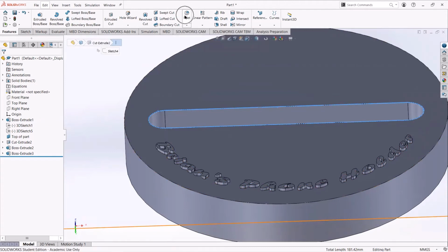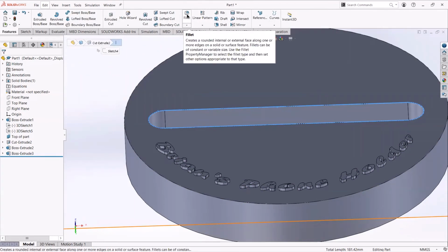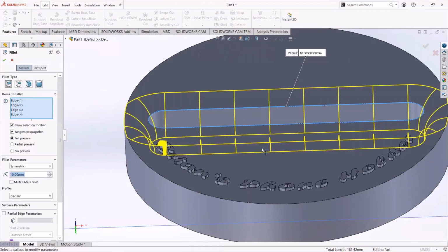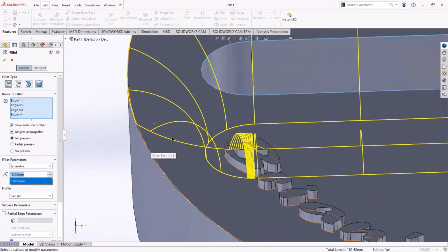And specifically, it's called fillet, and that button, fillet, is right at the top, and it'll only show up when you're under features. So if you're in Sketch, it won't show up. So you have to go to features and then fillet, and you click on fillet, and then it'll ask you for what radius do you want to fillet your part at. So radius basically means if you had a circle with that being at its edge, how far from the center would that radius go? That's why you see this curve right here. That's the radius specifically that it's talking about, this to its center.